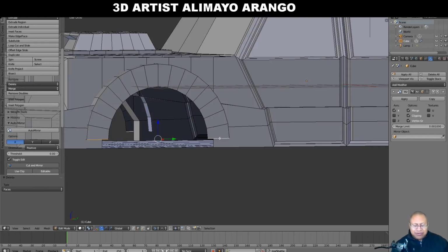The connected proportional editing tool allows us to move more than one vertex, edge, or face at a time, and it also allows us to not move what's right next to where we're selected. So it will only affect this object. With that said, we'll press G and then Z, and we'll just pull that down like that. Then we'll press A to deselect.